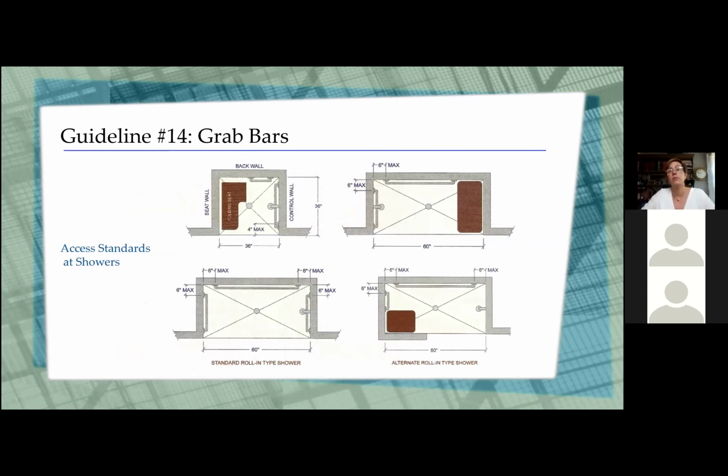More grab bars, these are in showers. We don't have them on the back wall of the shower here because you're sitting on the seat and trying to get yourself pulled up. Same thing here. Same thing in this one, you've got them on all three, so you're rolling in. You're probably in the chair at this point in time, so you may need those to help yourself maneuver around left and right, as well as get up.